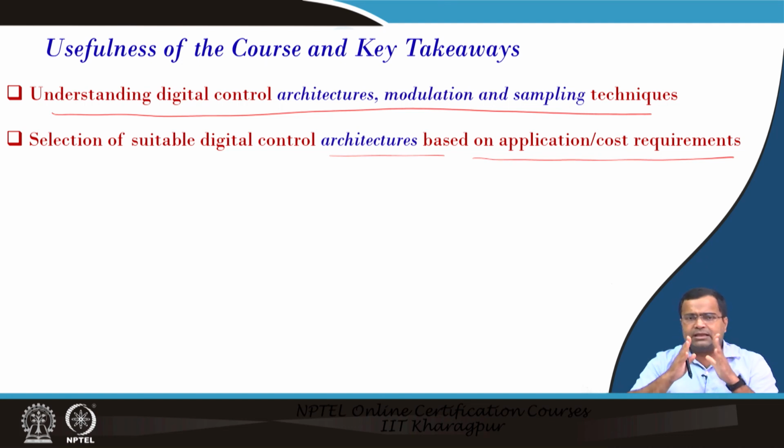We have discussed server applications where the digital controller IC is used to centrally control all the phases. Similarly, if there are multiple POLs for automotive application, you can have a core digital processor which runs the algorithm. It can have a central algorithm and communicate with multiple converters. So all these features are very helpful.